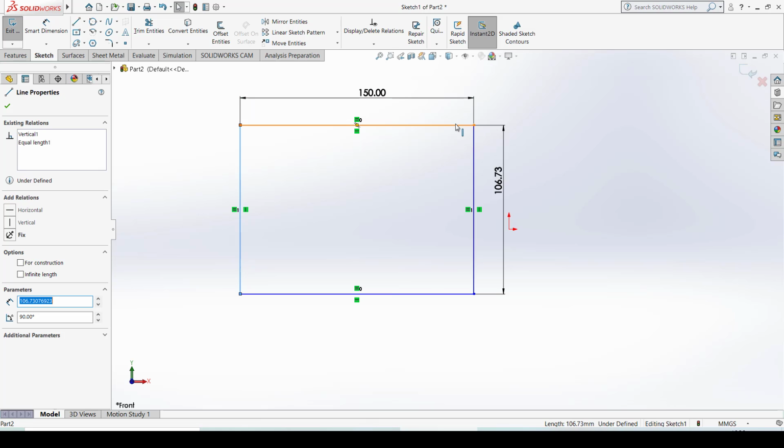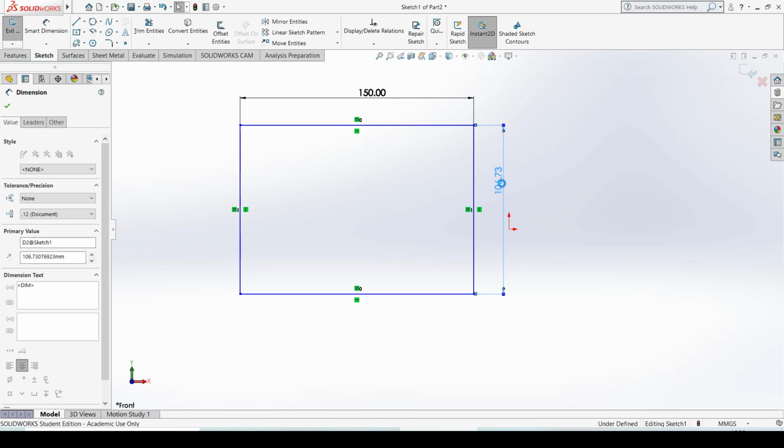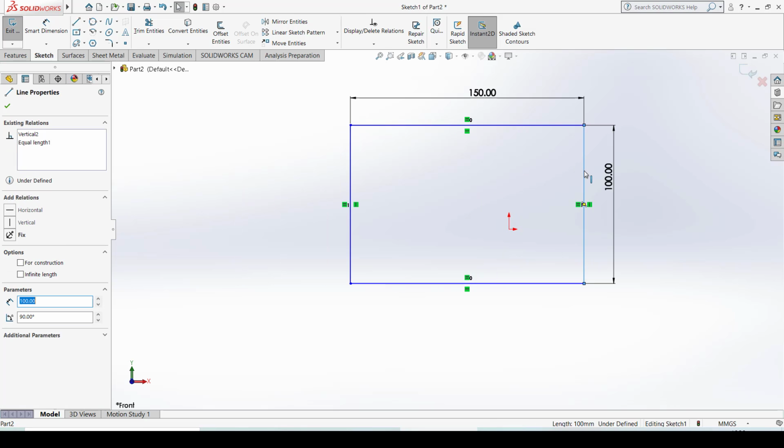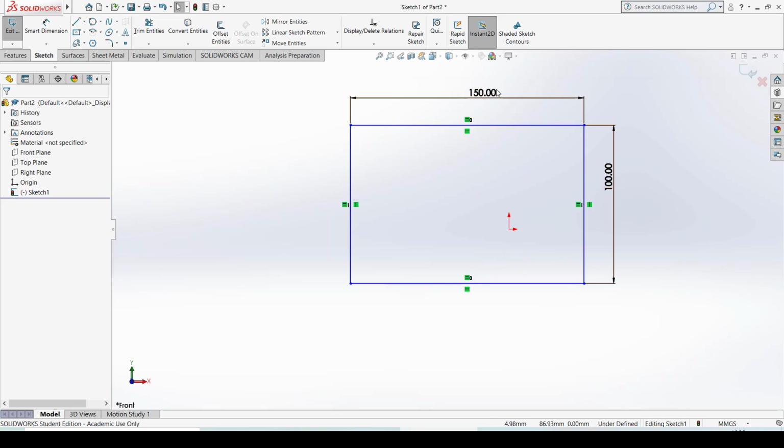But when I define the length of this box, you can see the whole box moves from one point to another. So this is how you can constrain the objects dimensionally, so that this entity is of only 150 millimeter length, and this remains 150. It doesn't change to 160 or 140. Similarly, if you give 100 to this width, it remains 100, not 90 or 110 or not even 99.